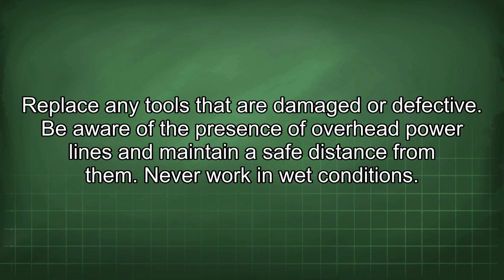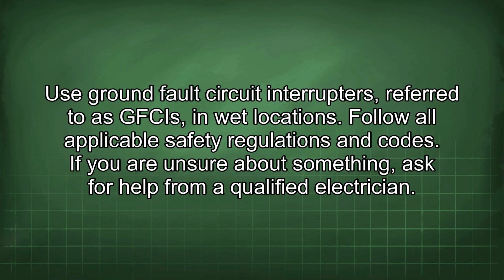Never work in wet conditions. Use ground fault circuit interrupters, referred to as GFCIs, in wet locations. Follow all applicable safety regulations and codes. If you are unsure about something, ask for help from a qualified electrician.